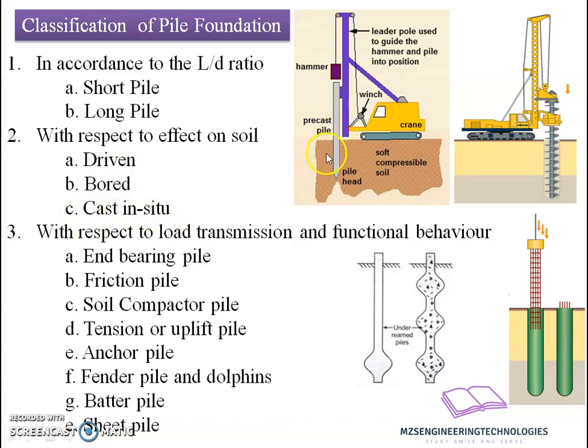In case of driven pile foundation, we are going to apply a load on the head of this, and due to the impact, the pile is going to insert slowly into the ground. Thereby the bearing strata will be achieved, and there we may have some advantages, like during this there will be certain resistance over the pile, the friction force will be there, that will make an additive effect in the